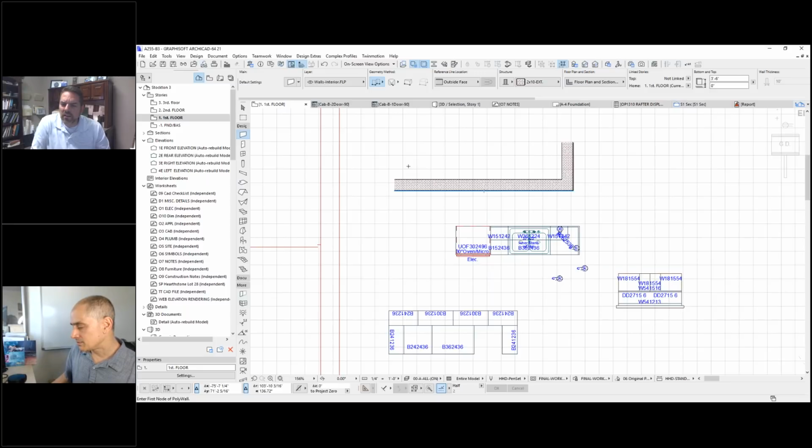One thing I'll add, and you may have a tip for me on this one, is when I'm migrating or updating ArchiCAD, say for instance version 20 to 21, and all of my old objects on my worksheets are version 20, what I normally do is load both libraries, the old version, the migrated version, and the new version.